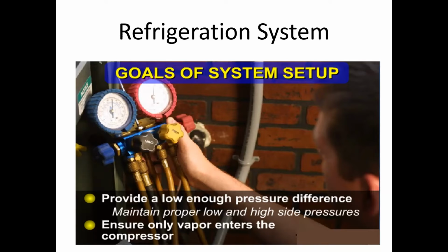The other thing is that liquid is going to pump the lubricant, or it's going to pump the oil out of the sump of your compressor. And now you're going to have that compressor running with no lubricant, and you're going to start to have wear on those bearings, and that's going to cause your compressor to fail.